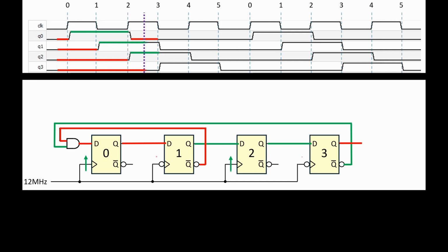At time 3, latch 1 copies the Q0 low, and latch 3 copies the Q2 high. At time 4, Q1 and Q3 are not both off, so D0 remains low and Q0 remains off. At time 5, Q1 copies the Q0 low and Q3 copies the Q2 low. On the rise of the next oscillator edge, D0 is on, raising Q0 and starting the whole cycle again.